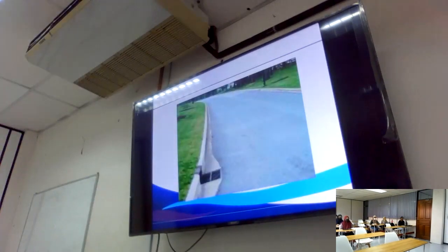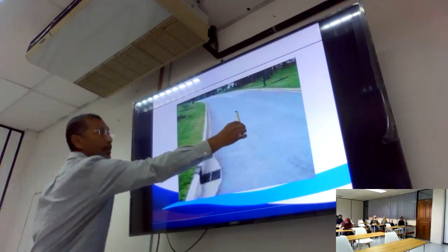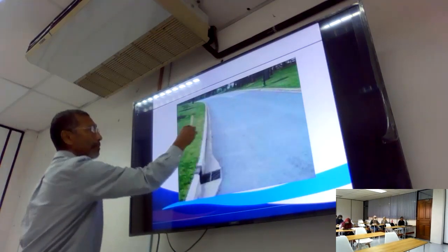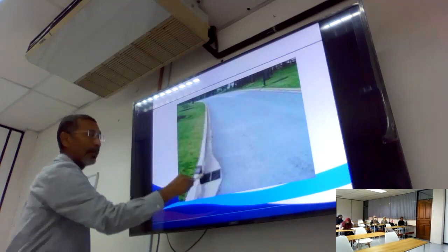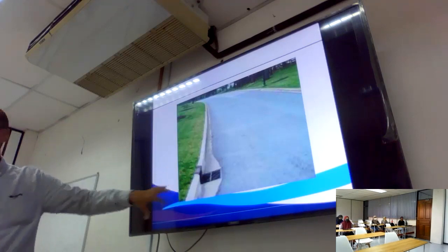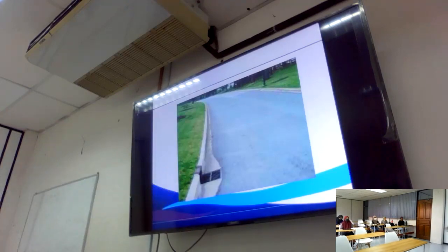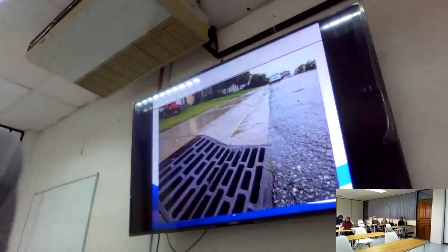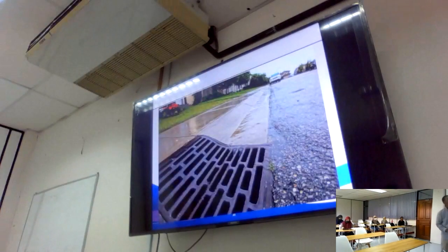This is what I called just now a curb drain, right? Curb drain. The water that falls onto this road and comes down here will go into this drain and into this inlet, the roadside inlet, that goes into the underground pipe system. In some places there is a grating like that, from the curb. So it flows from the curb to that grating and goes to the drain below.